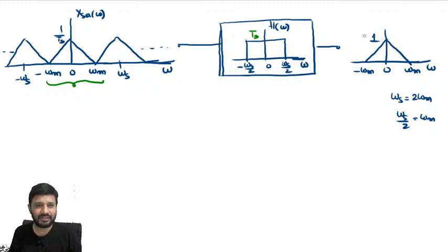See, this is in frequency domain. Frequency domain is one way of analyzing the signal, the other way is in time domain. Sometimes time domain analysis is difficult, so we go for frequency domain. Observe how much easier. Pass this periodical repetition through a low pass filter. So the frequency response, this is the pass band of the low pass filter. So the signal between minus omega m to omega m will come. How much easier it is.